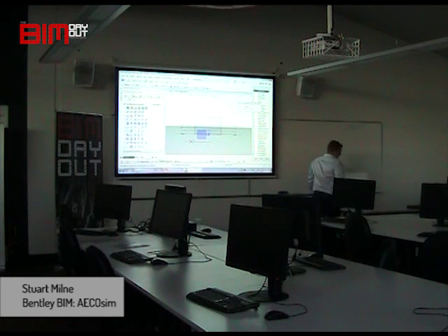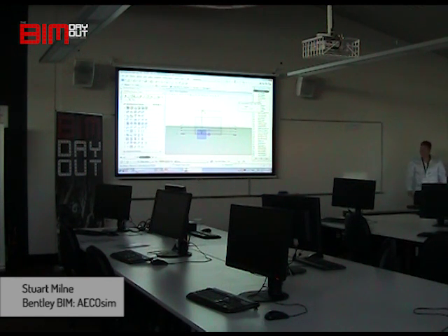Okay, so once you've done that, then all you need to do, like we did in 3D with AccuDraw, is point in the direction that you want to go. So we actually want to copy it up this way. Let's say we want to copy it 3 meters. We type in 3, 1, 2, 3, and then we click. And then it will still be hanging off your cursor. You can type in 3, 1, 2, 3 here, 3 meters and click.